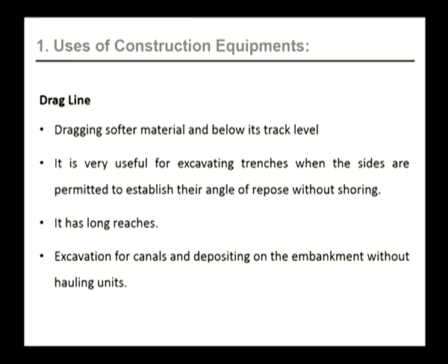It is very useful for excavating trenches when the sides are permitted to establish their angle of repose without shoring. It has long reaches. And the next point is, it is used for excavation for canals and depositing on the embankment without hauling units.